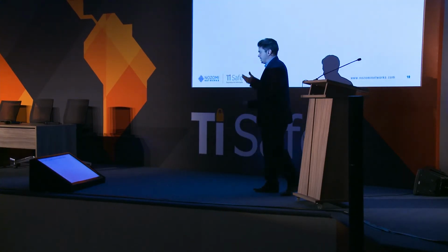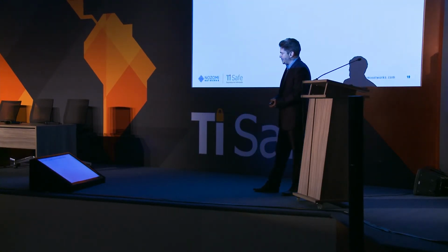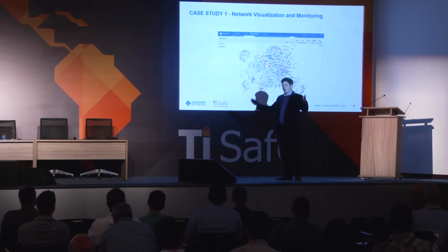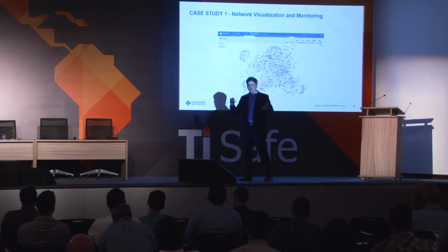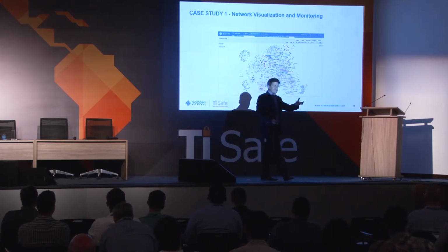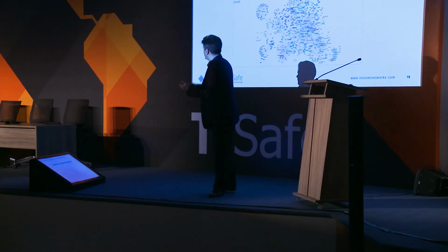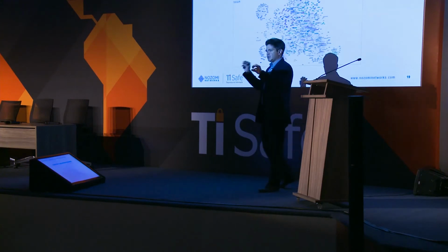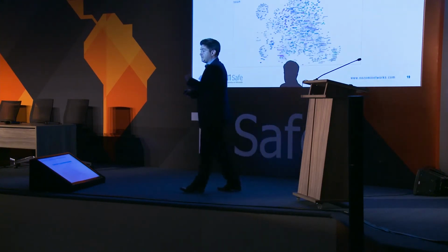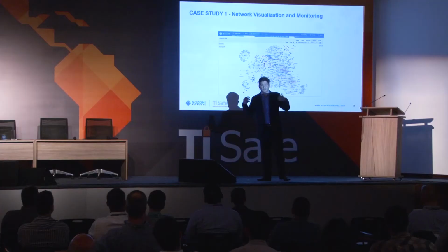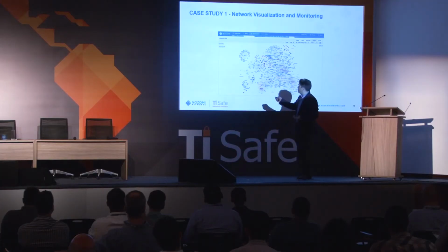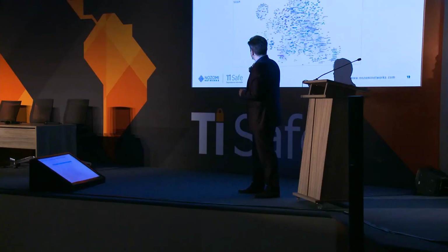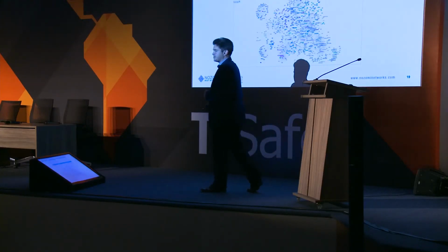So this would be a tool, and of course, this is an implementation with Nozomi, where we would first discover his entire network. We go into a process where we start learning about the network. As soon as we learn about a node, we start classifying the behavior of that node. You cannot really see it from there, but the color coding starts happening slowly. And it really reflects the role that the different nodes represent in a network. For example, the blue nodes are PLCs, or slave roles. The red nodes happen to be SCADA masters.